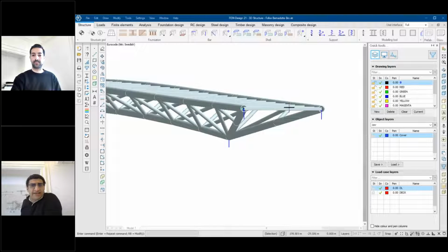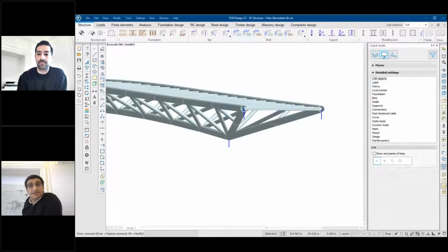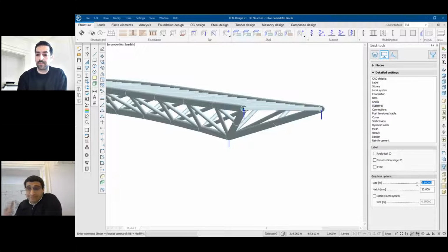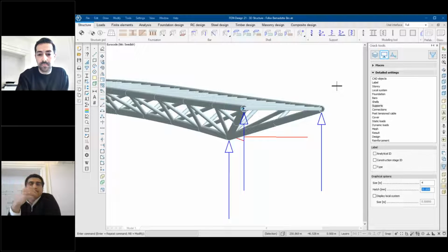So guys, we can increase the level. From the conceptual design point of view, you would see that there's quite a high difference between the upper line of the supports and the lower ones as well. So that's giving you a lever arm, and just by looking at the geometry, you will have a rather high rotational stiffness there. So you would actually expect that from the conceptual design idea.